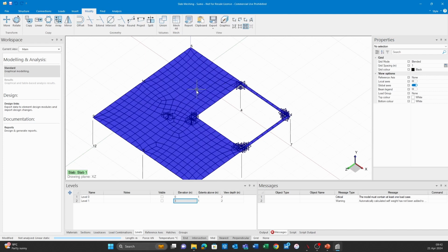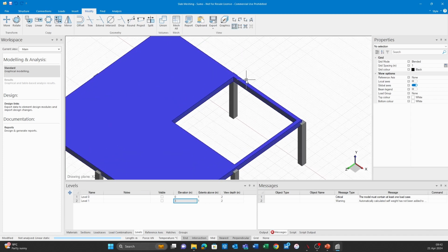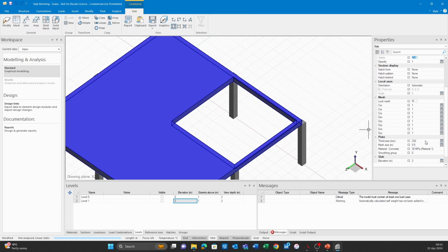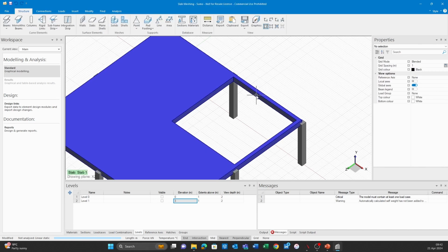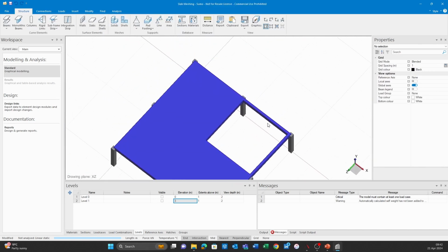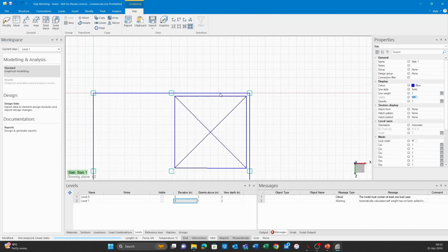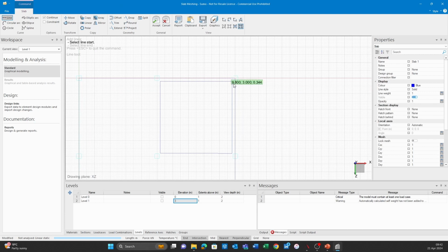What I'd recommend here is that we actually change the layout of the slab, and we add beams here that are the shape of this cutout, or this portion over here. So the slab is 330 millimeters thick. This is 200 mils wide. And what I would do then is I'd go to my level view, I'd modify, and I'm going to change. So I'm going to remove this cutout completely.